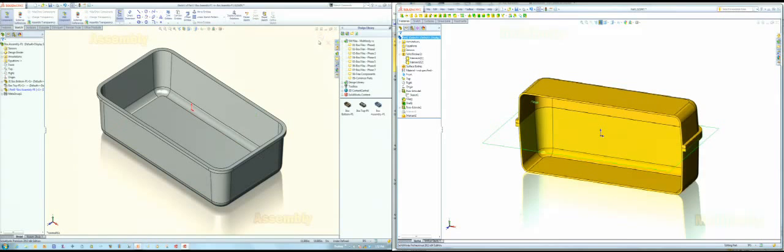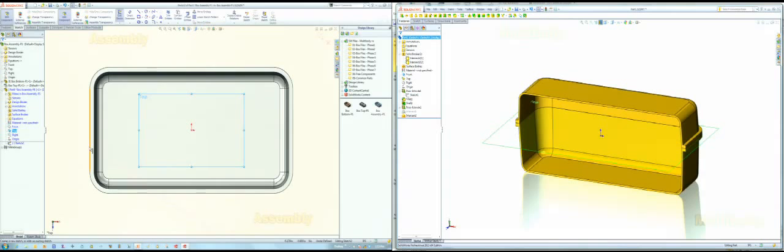And I'm in a sketch, that happens automatically, but the sketch I'm in is on the front plane of the part, and I really want to put it on the top plane of the part so it matches the top of the other box. That's easy enough, just get out of the sketch and create a new sketch. So in this case I want to start on the top plane of the new part. I want this sketch to look exactly the same as that sketch on the bottom of the box.